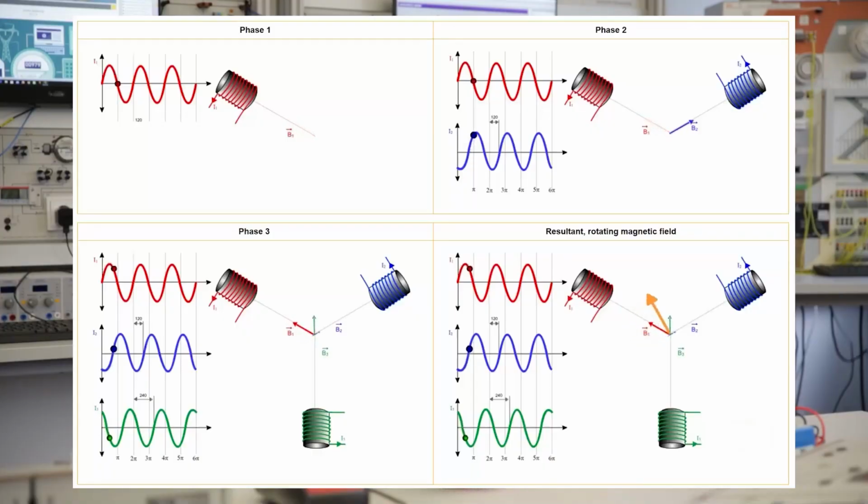In the picture, you now see an animation that shows how the electric motor works, or more or less how the rotating magnetic field is created within the stator by the three different coils, which are controlled by the inverter. All the coils have the same sinus voltage regarding the amplitude, but there's a phase shift.